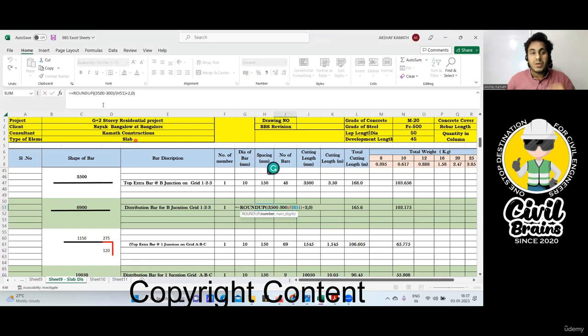So number of bar, what have I done? This is 3,500 I have taken. But this includes even the beam thickness. So what I did, 3,500 minus the beam thickness, which was 300, I deducted from that. In that way, from the face of this side, I got the length, and from the face from here, I got the length. Now this I'll divide by spacing, which is 150. Now I need to do +1 or +2. I need to do +2.